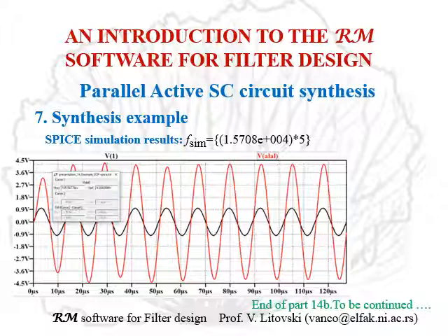But since there is switching, it may be a problem when implementing real operational amplifiers with finite slew rate, and that may bring results which are not ideally equal to the ones reported here, which are also out of the scope of the synthesis program, since we never know in advance what will be the operational amplifier used by the filter designer.